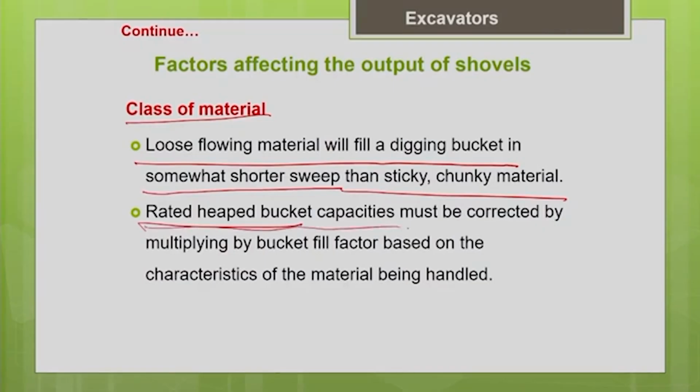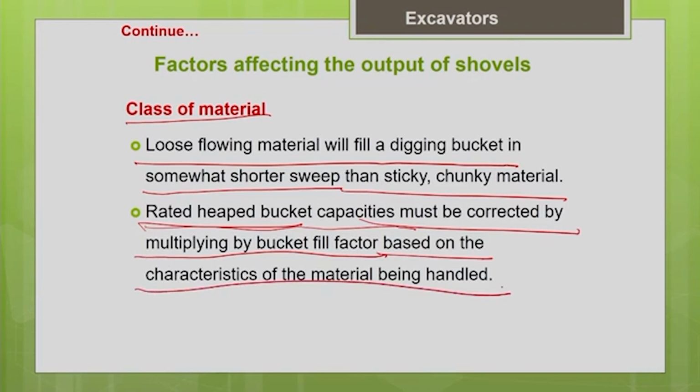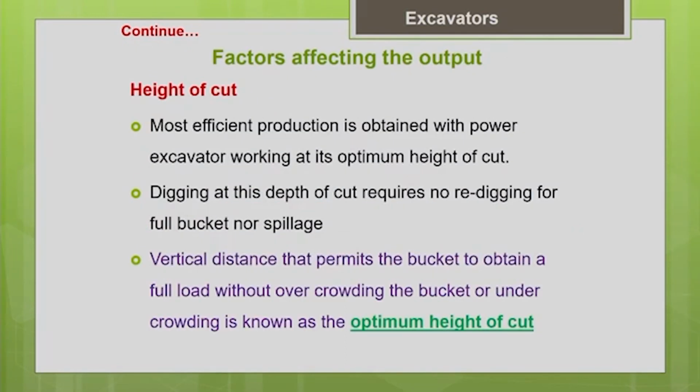Rated heaped bucket capacity must be corrected by multiplying by the bucket fill factor based on the characteristics of the material being handled at the project site. Now another important factor which we are going to discuss is the height of cut. How is this factor going to affect the productivity? Let us see.